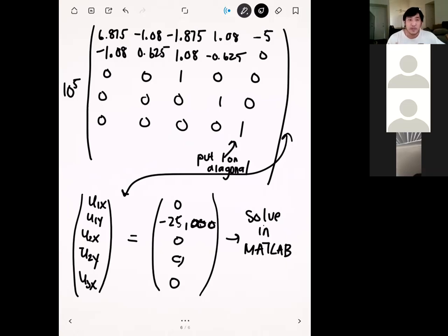Because it might be something that, basically what we're saying is that we're not able to solve for that displacement based on this. But right now we're still in relatively simple conditions because we're doing trusses, where trusses can only displace axially. But once we start adding beams and rotations and frames, I want you to do it this way, just so you capture everything correctly. Okay, any questions on the global system here?